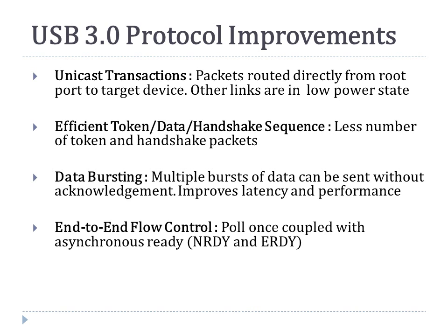Then there is an efficient token data handshake sequence. Fewer packets are exchanged to do the same transfer than in USB 2.0. It also supports data bursting, where multiple bursts of data can be sent without an acknowledgement, and this improves the latency and performance of the bus.